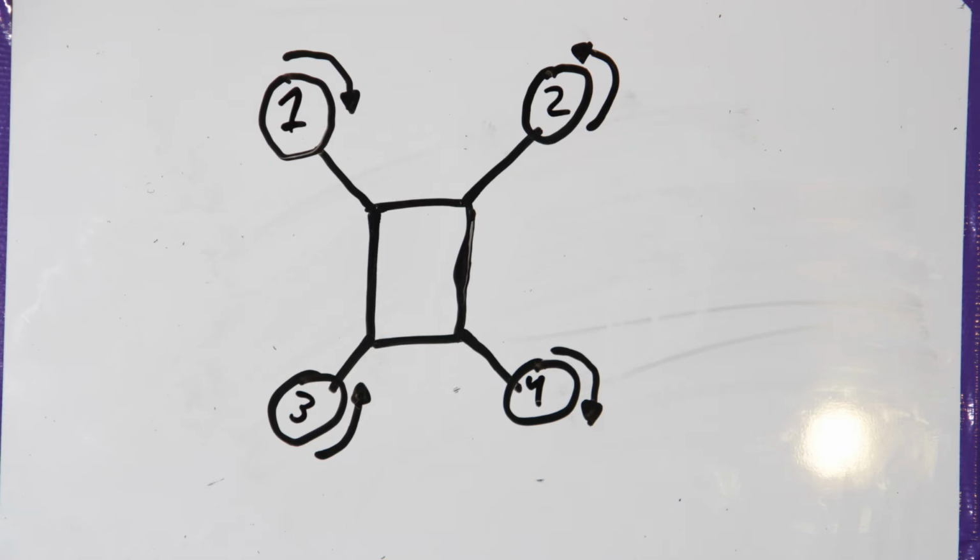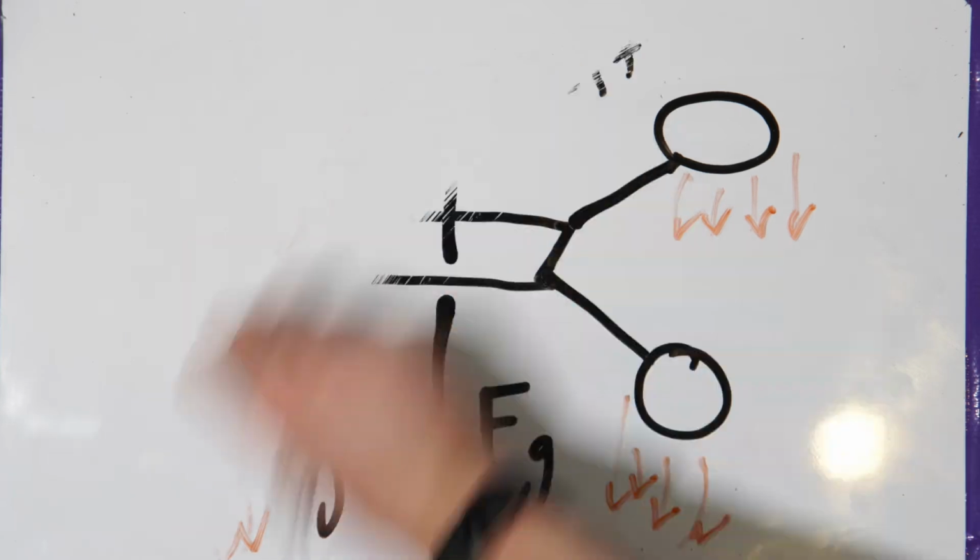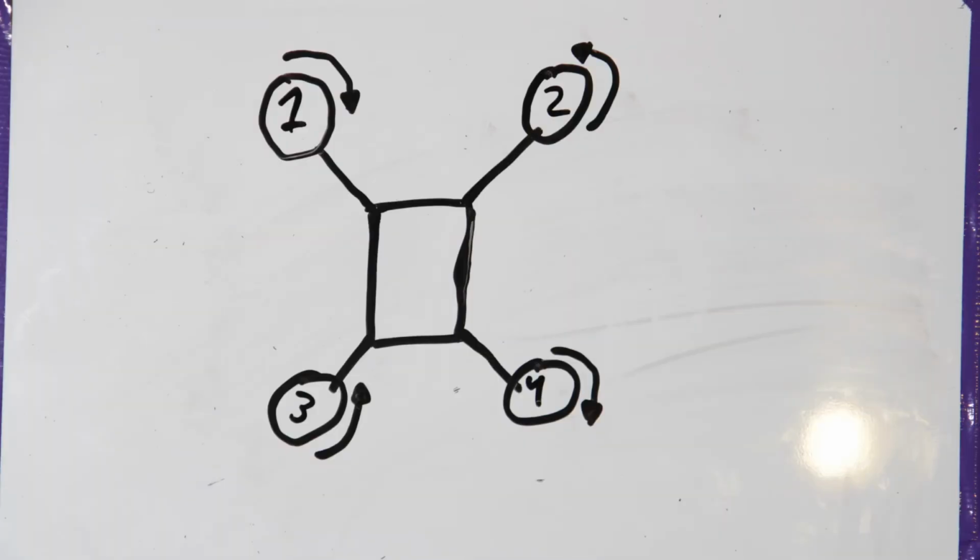These arrows represent the way that the propellers are spinning. As well as giving thrust, the motors possess torque, and when they are up in the air, there is nothing to oppose this torque, except for slight friction. So this is why 2 of the motors spin in the opposite direction, to oppose the torque of the other motors and vice versa.